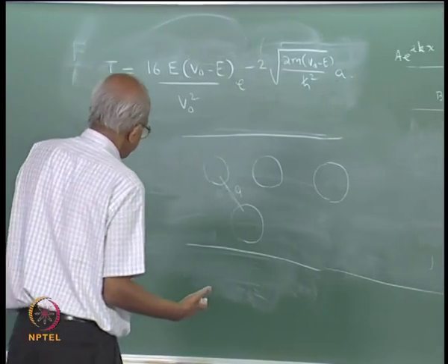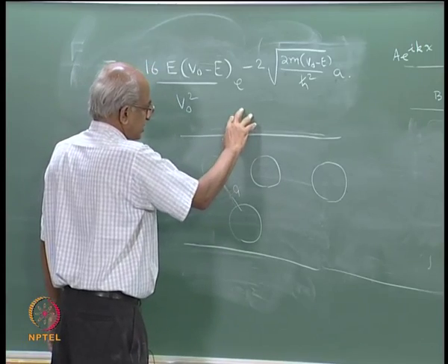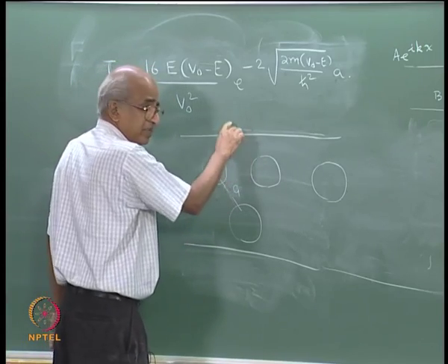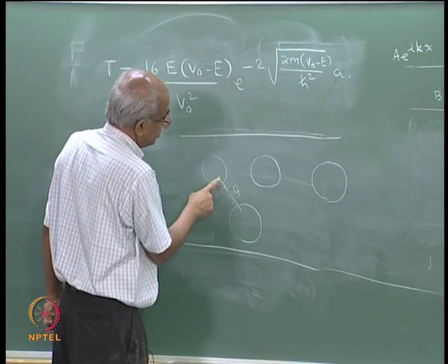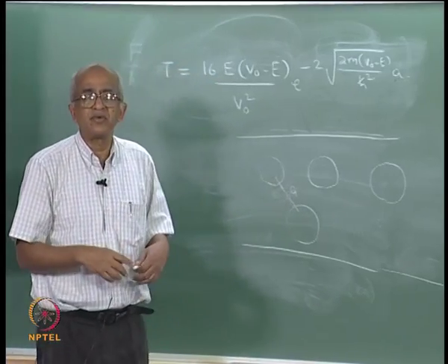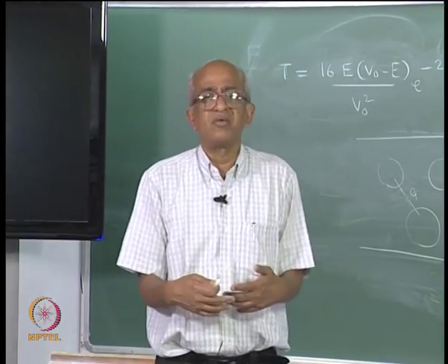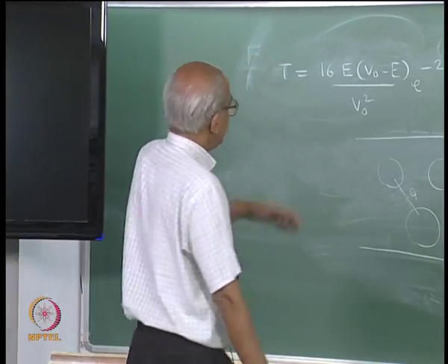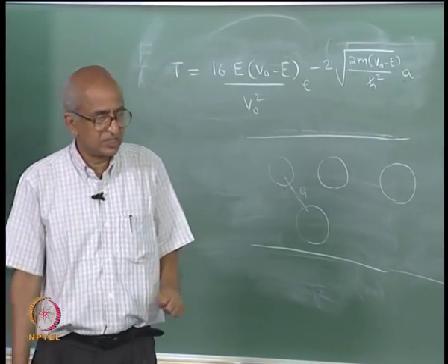Okay. And now imagine you touch the film from the top, then you are applying pressure on the film, as a result of which this distance will change, and hence the tunneling probability will change. Therefore, the current that can flow through the system, the conductivity of the system, will increase very rapidly if you just touch it, and this has been used to make touch sensitive screens.